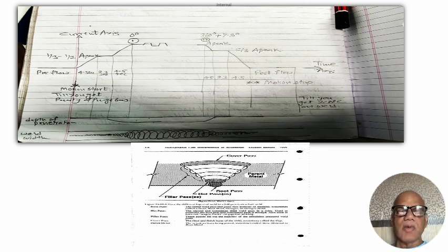You then press the next trigger, and that starts a small upslope towards the initial current, which is about one third of the final current. And at this stage you check whether all the systems are working well. It's a very small current, it doesn't damage the material, and at that stage you actually start the rotation. That means the movement between the torch and the job: either the job rotates or the torch starts moving, or if it is orbital welding, the torch inside the tube will start rotating, or the tube will start rotating.